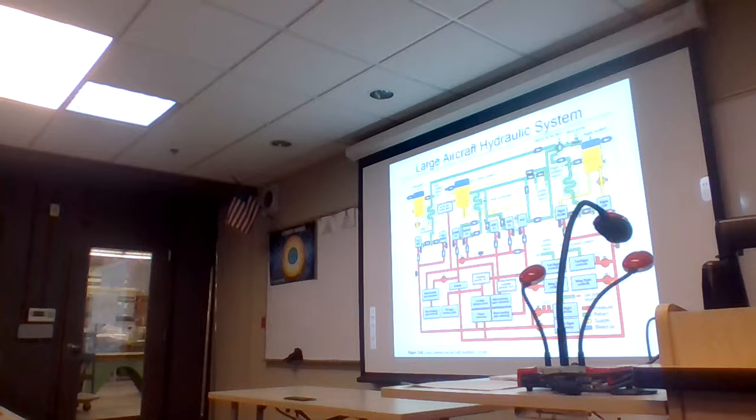We'll talk about that in much more detail later in the class, but it's an air-driven pump, and in some cases for some aircraft an air-driven generator. It's extended into the relative wind in the event of complete hydraulic failure, and it supplies essential hydraulics for the aircraft if everything has gone out. In addition, on many aircraft, they have a device called a... does this have a PTU?